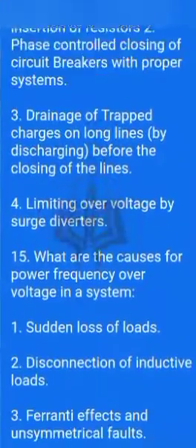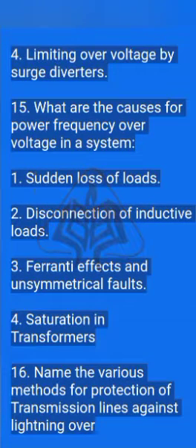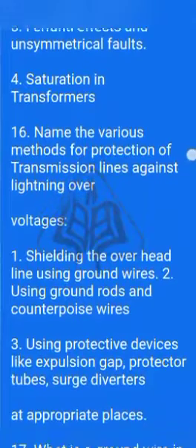15. What are the causes for power frequency overvoltage in a system? 1. Sudden loss of loads. 2. Disconnection of inductive loads. 3. Ferranti effect and unsymmetrical faults. 4. Saturation in transformers.